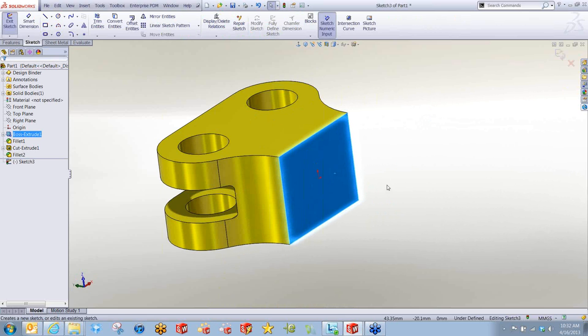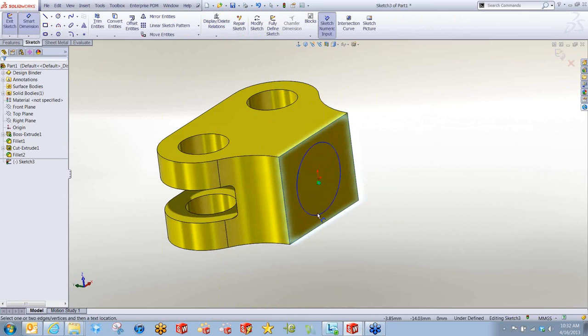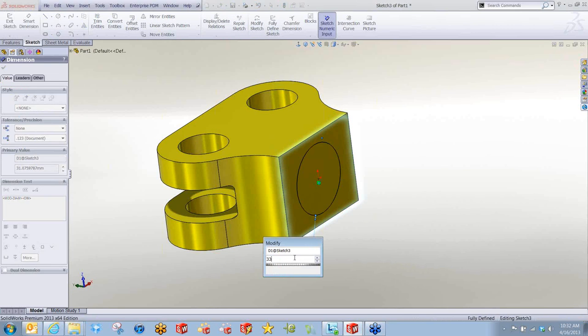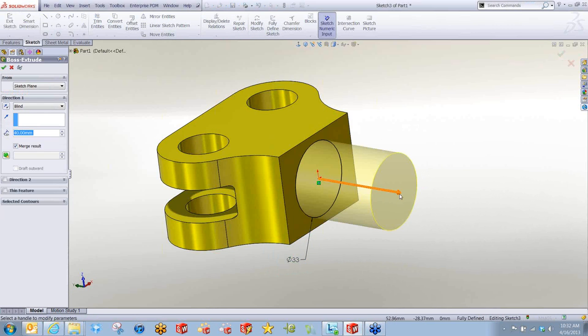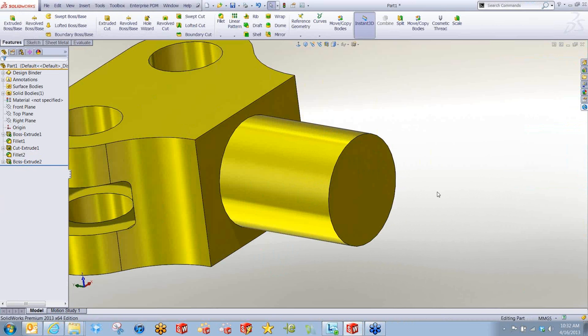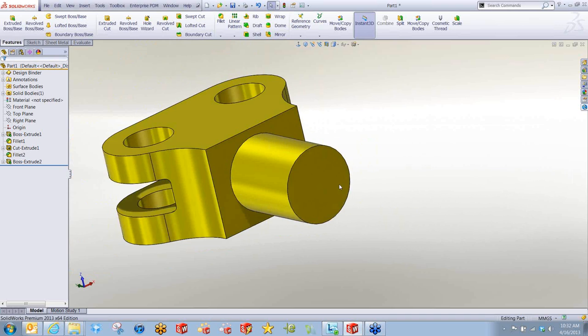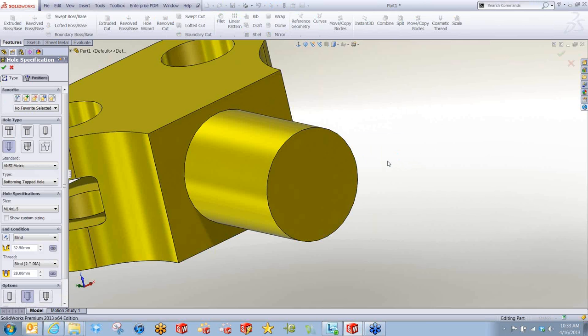All right, now we're ready for our last boss here. Again, we'll just gesture our sketch tools, key in some values, and we'll go ahead and extrude this out. All right, I'm almost done with the model, but now I need to start tapping some threads onto this, that way we can thread it into our final assembly. Okay, and we'll start with our hole wizard.